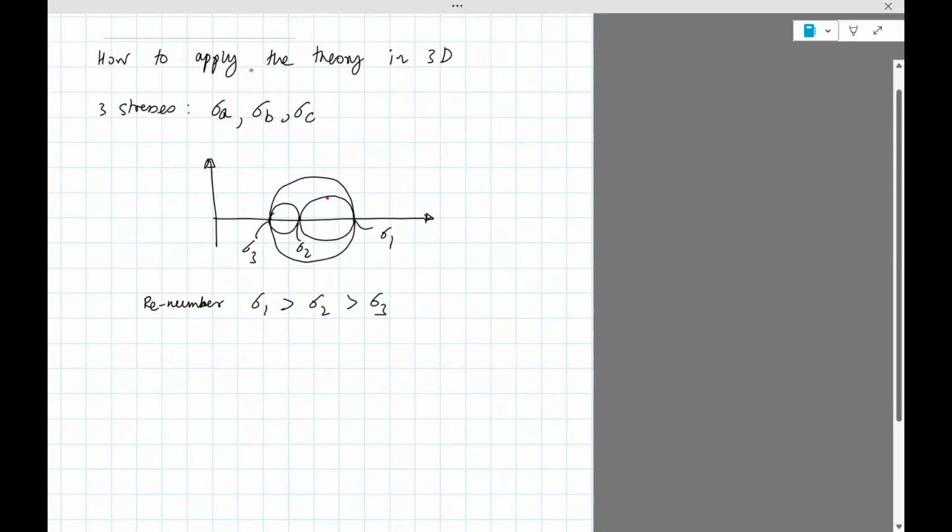Okay, clearly this is the maximum shear stress for the in-between circle. This is the shear stress for the smaller circle, and this is the stress for the larger circle. This happens to be your critical stress. This is tau max. This is the failure which will determine failure. It won't be the smaller stresses because they have a smaller value.